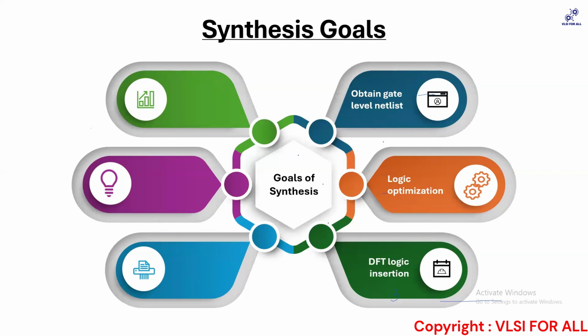The DFT team can do the insertion and then pass it back to synthesis, and they'll do a lot of checks. So what happens in the DFT logic insertion? As I explained, they have a notion of how many flops to convert to SDF. When I say SDF, guys, please understand this is nothing but scannable D flip flops, scannable flops. Normally D flip flops are the ones majorly used in the industries.